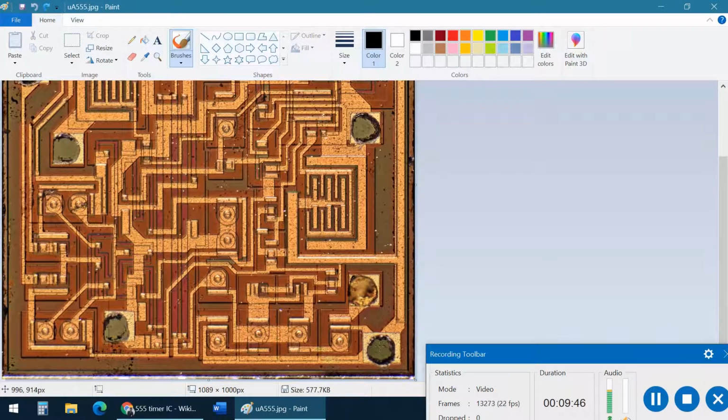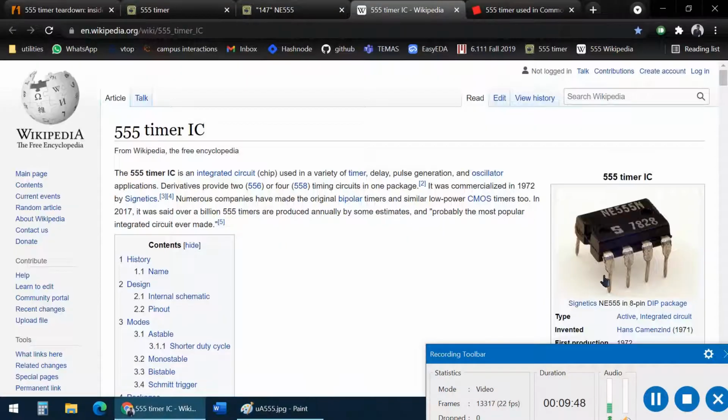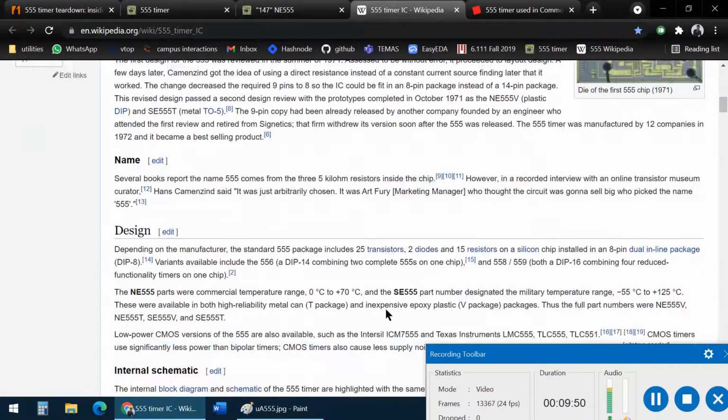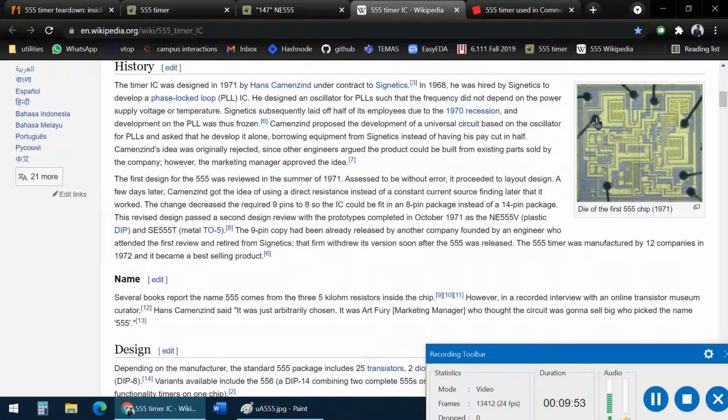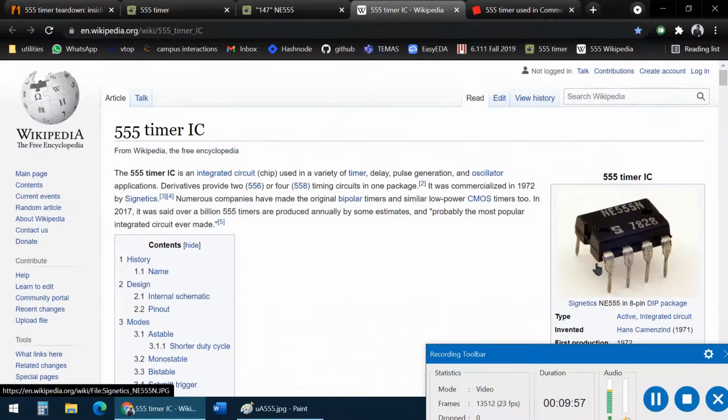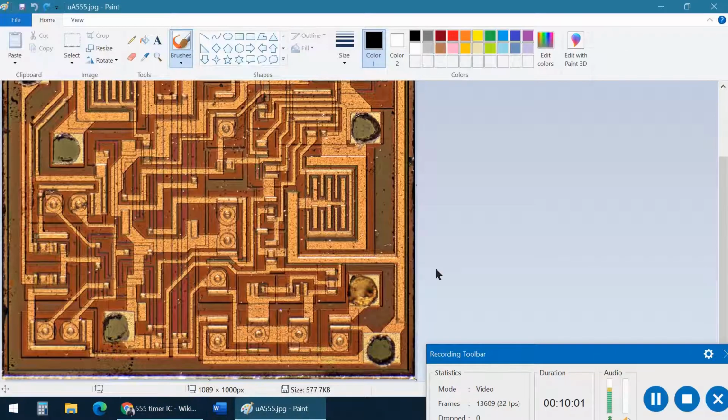These are the pads, and they're connected to the pins via something called a bond wire. You can see in this figure, there's the pad and the bond wire, and the bond wire goes to the metal contact which is outside the IC. So we know we have 8. Now we have to correspond each pad to one of the 8 pins.